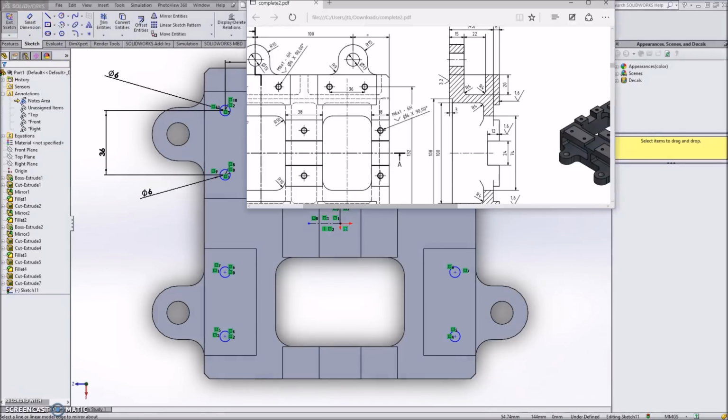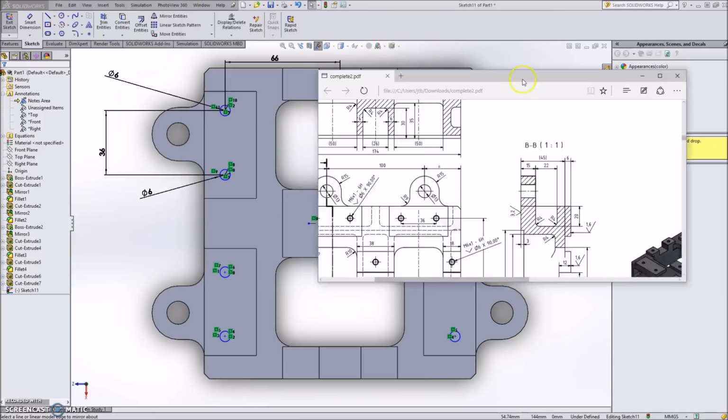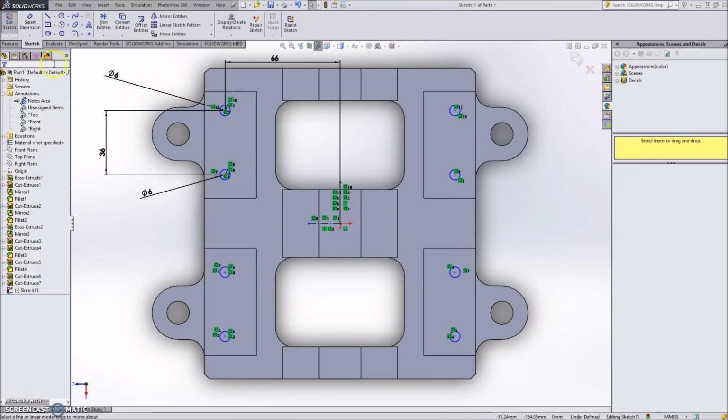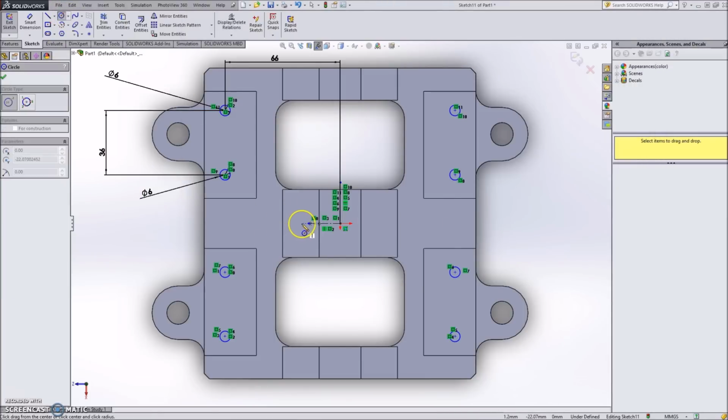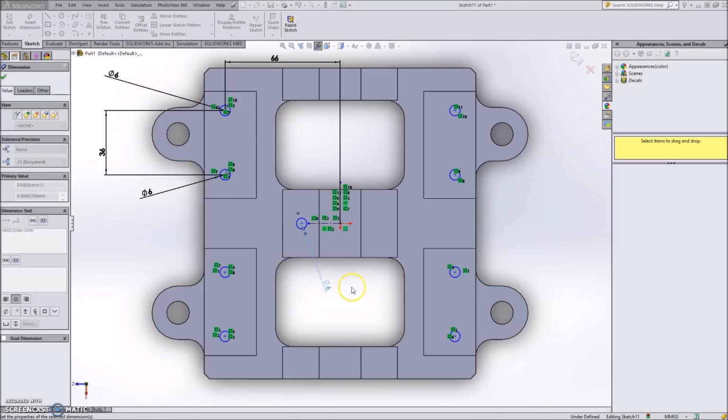tabs. So to get these holes into the center tabs, all we have to do is center each one of the holes onto each one of the individual tabs, and we see that they are also 6 millimeters in diameter. So let's begin by drawing one 6 millimeter circle here. And we notice that this overall gap was 66 millimeters. This gap in the middle is 24, which means that this was 33 minus 12, which gives us 21 millimeters wide for each one of these tabs.